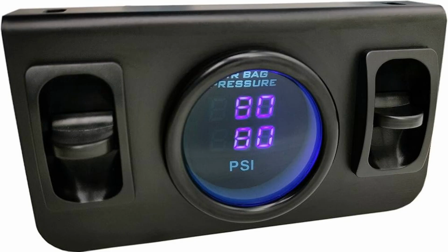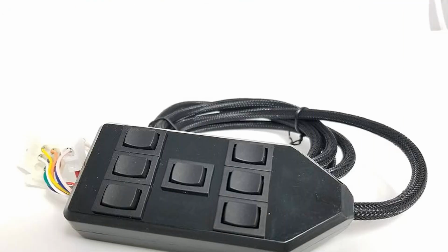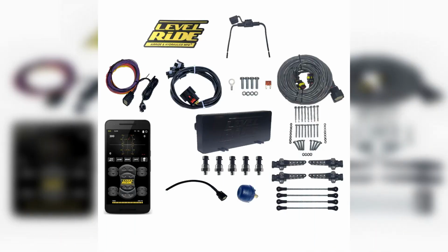Pneumatic elastic element, which has the main role in supporting the body. Hoses, fittings for tight connection of the system elements. Sensors of level and acceleration of the body, used for automatic adjustment of the body position. Compressor temperature sensor. Sensor of air pressure in the system. Control unit, which receives data from the sensors and controls the actuators. Control system valves. They are needed to pressurize the pneumatic elastic elements, to relieve pressure, to maintain pressure in the receiver. Structurally, the valves are located in the solenoid valve block.